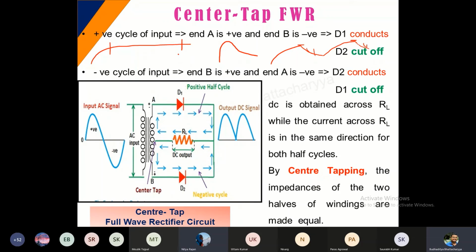If we focus only on the charging part, we can prove that by increasing the capacitance value, we get an output like the one I've drawn here. You can observe that this is a constant DC supply. So the efficiency of 80% is increased to around 85% to 90% based on the capacitance being used. But for a pure circuit like this, it will be around 80%.